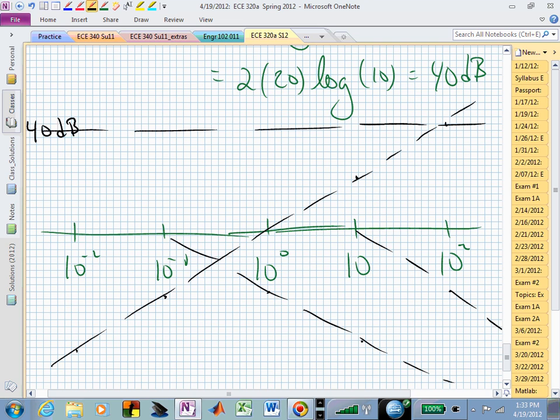So that if I put all of those pieces together, now you have to kind of keep track of what's going on, just like we did before. And I like to sort of go as far back to the left as it makes sense. In this case, I want to go all the way back before I see any of these breaks to maybe here. And I say, okay, where can I start my resulting plot? Well, this guy's contributing minus 40. And that one's contributing plus 40. So I can actually start my plot right here at 0 dB.